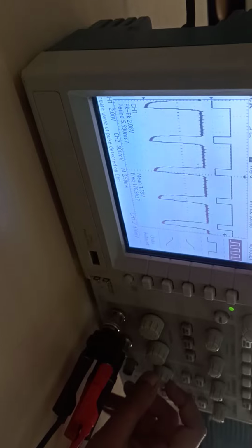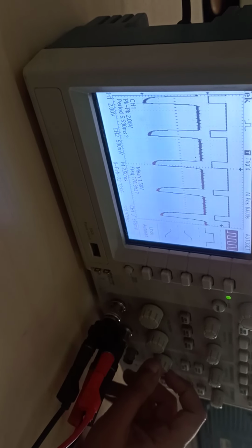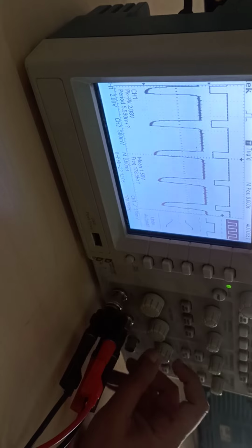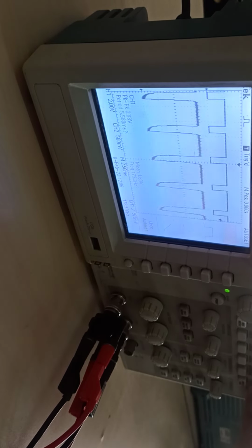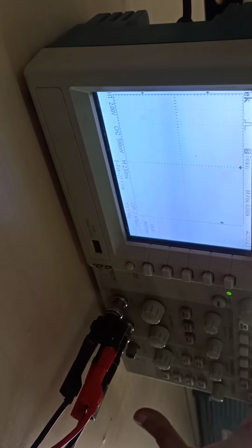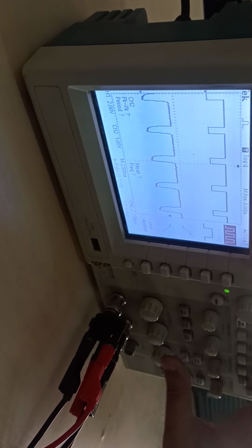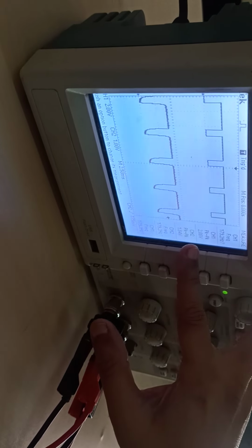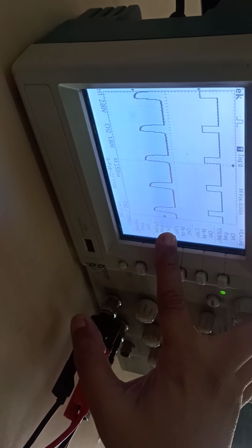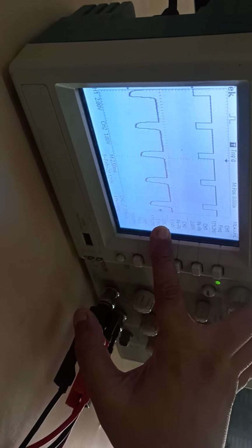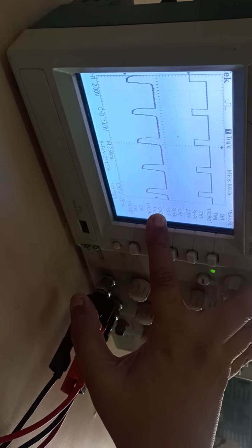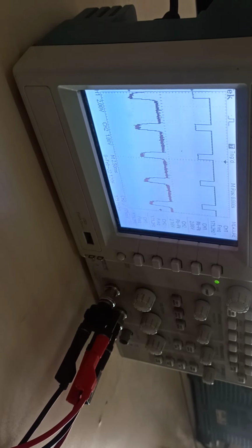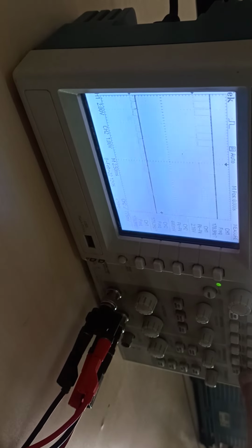Op-amp output is connected to the 4K7 only. So 4K7, this is the op-amp output. So we can measure it. So we are going to get channel 1 as 2 volts and channel 2 amplified with 1.84 volts with 4K7 input. Now I am connecting R1 again and measuring it,